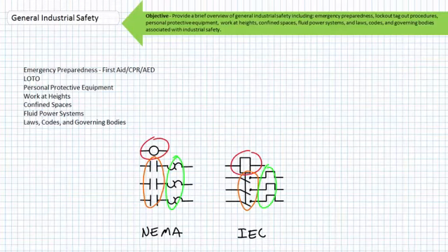Consider a specific application in which there are 9 divisions of available NEMA contactors, and for the same application, 14 divisions of IEC contactors. Each NEMA contactor covers a broader range of acceptable operation points, and each IEC contactor less. The NEMA contactors are more robust, but they're normally bigger and more expensive. The IEC contactors are lightweight and less expensive, but they don't have as wide of an operational range, and you really need to know what you're doing when you're sizing an IEC contactor because numerous operation parameters come into play.